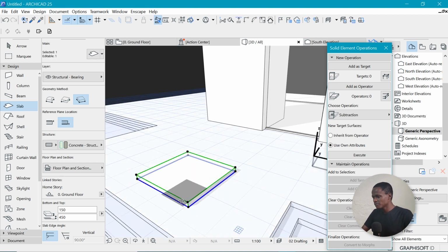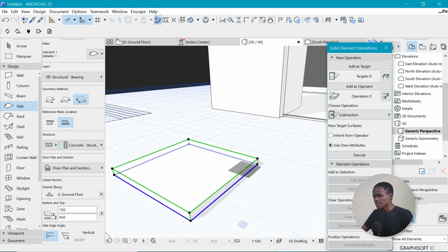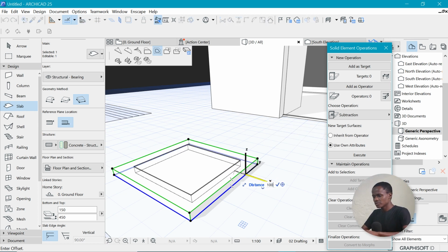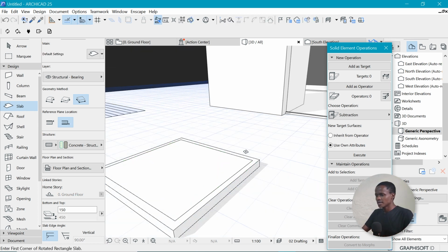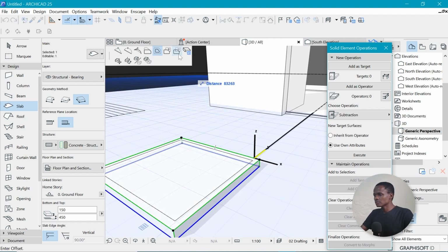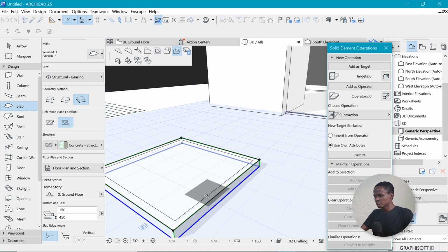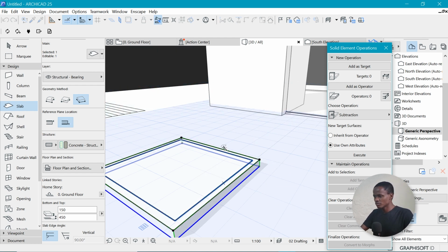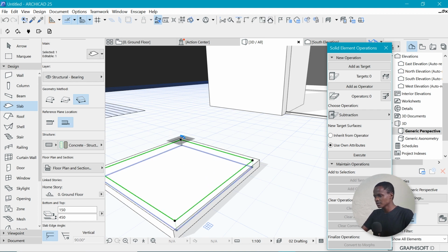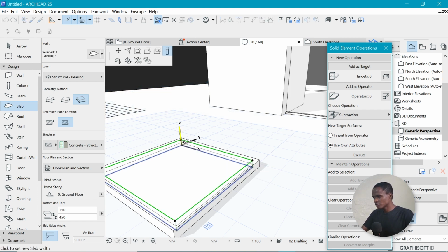And let's make a copy of it in order to create that inner portion. And extrude it inward by about, I don't know, 100, and make sure we subtract that from this polygon. So clicking on the edge, we choose subtract from polygon and space, hold down the space bar to remove that section. It has been removed. So now if we select this one, we can extrude it downward.